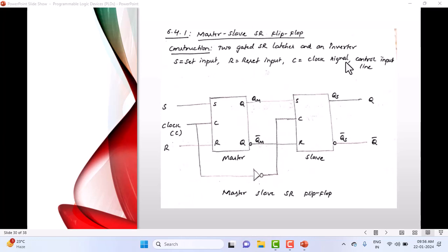Understand? I always compare this with the train analogy. If you remember, always compare the clock with the train, and let me help you understand how exactly this edge trigger plays a very important role. Look here, whenever the train comes here, let us say, when the rising edge comes, the train is coming and stopping at a particular place, nothing but the rising edge coming here. When the rising edge comes, you can interpret the input like a passenger. This must be ready well in advance. The train will not wait for the first rising edge when it comes here, and if you miss that, what will happen here? When the first rising edge comes, whatever data is there, it will take and change its state.